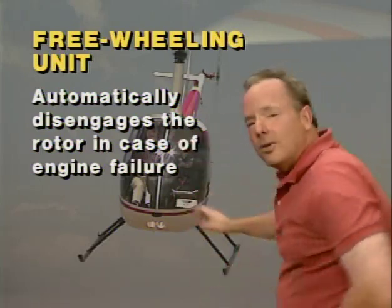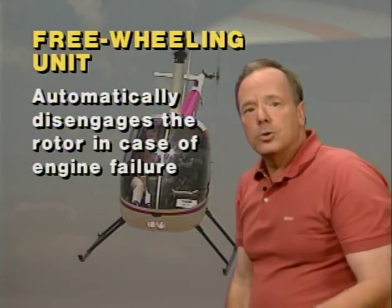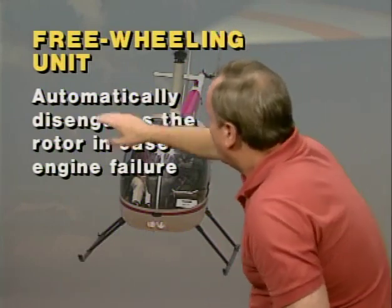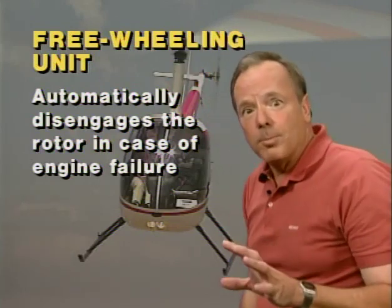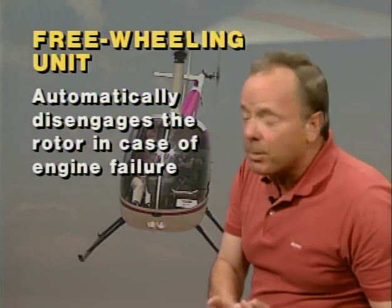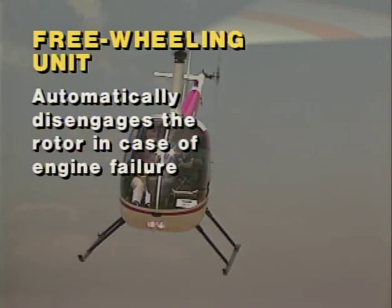engine failure. Now, they're going to ask you on the test, why do you have a freewheeling unit? And one of the things they'll say is to reduce or relieve the starter load. No, that's not correct. You have another clutch for starting the engine. The purpose of it is to allow you to be able to fly the aircraft in the event of an engine failure and to keep the rotor RPM up. Now, they'll also say so you can practice autorotations. Well, it's true, you can practice autorotations, but that's not the purpose of it. The purpose of it is to disengage the rotor in the event of, and terrible thought, an engine failure.